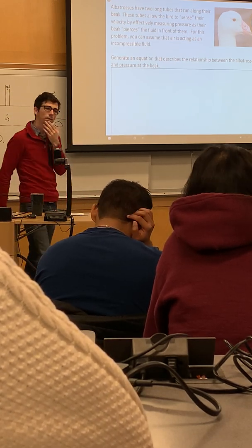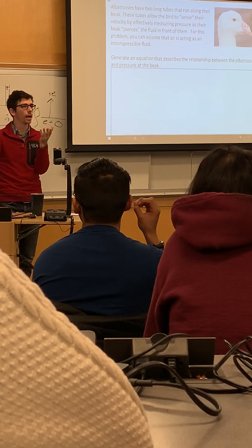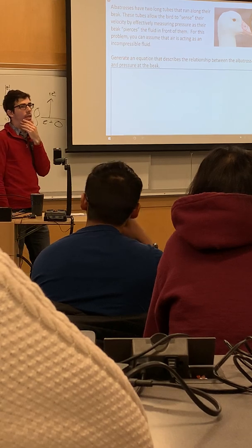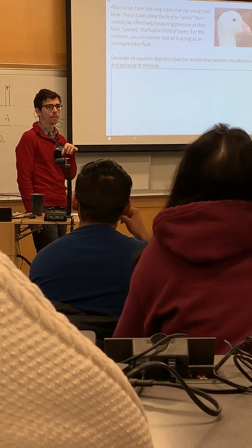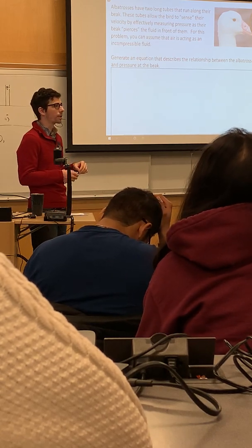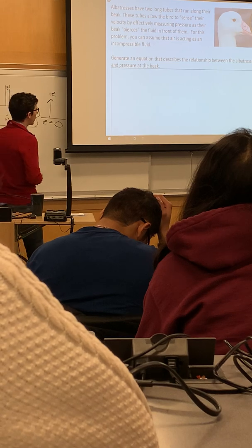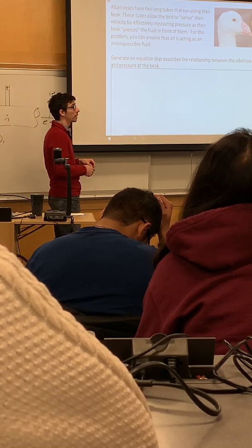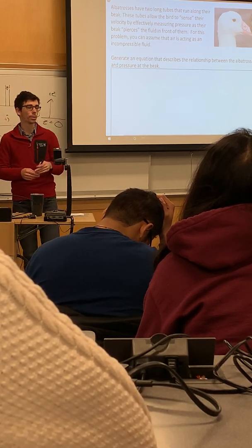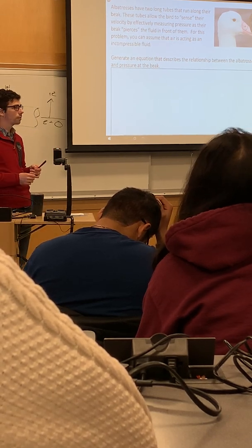Does our Bernoulli equation still work for gases because we're incompressible? Yeah, right. Which obviously in this case is a more limiting assumption because gases tend to compress at a much lower range of pressures. But if you get a problem that's not explicitly told that you should assume it's an incompressible fluid, then you can go and assume that gas is an incompressible fluid.